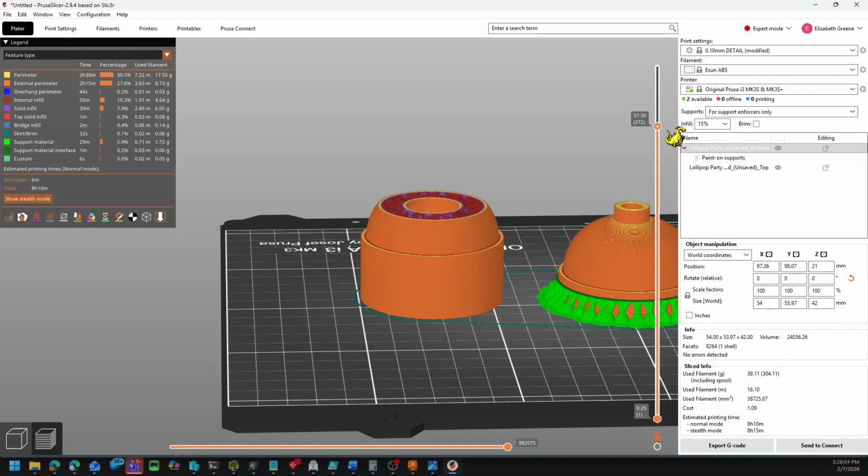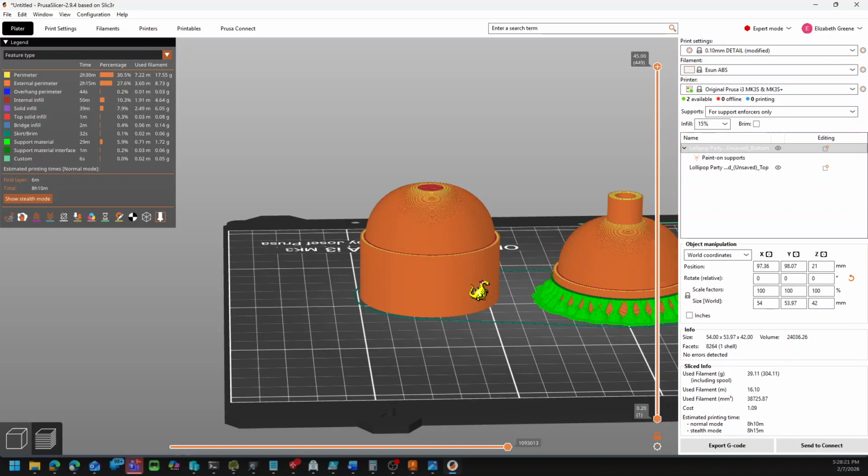Another thing you might consider is if you want a different appearance for these where it doesn't look like 3D printed layer lines, there's a fuzzy skin option that you can turn on, makes the outside surface of it slightly rough. That tends to help with the stair-step effect as well. I don't really understand why, but it does. So there's some magic in there.